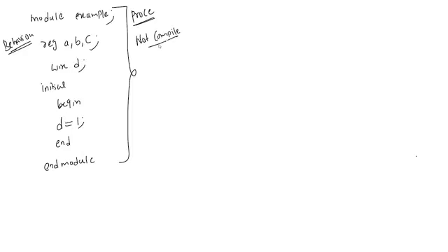Why? Because here D is which data type? Wire. I told you in behavioral modeling, the LHS should be which data type? Compulsory, it should be reg data type. The RHS can be either wire data type, reg data type, or it can be a constant, or it can be an integer also.